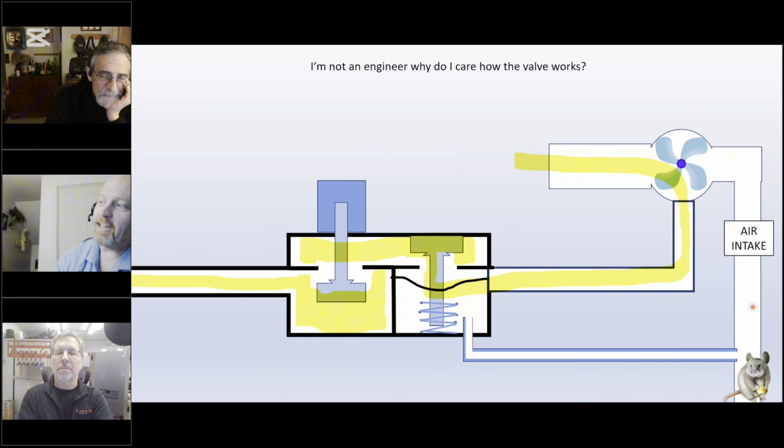Well, the same thing happens to the air intake. The pressure here is going to drop dramatically. That's going to have the effect of pulling down on this diaphragm, which is going to choke off your gas flow dramatically. And if the blockage is big enough and the valve is set correctly, we're actually going to just shut the gas off entirely.